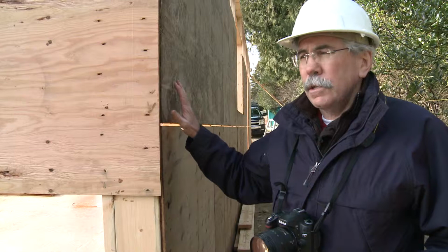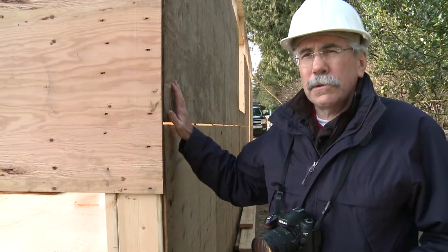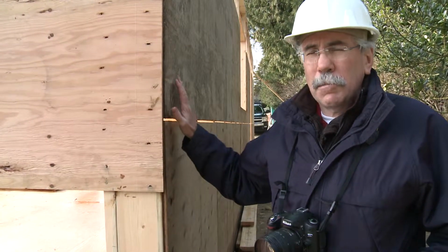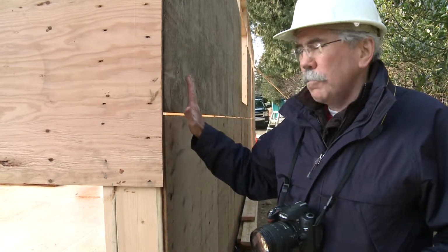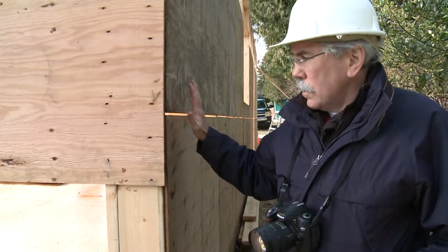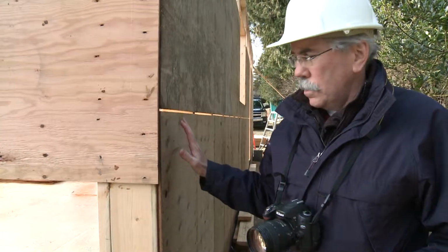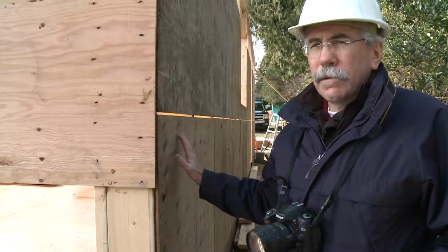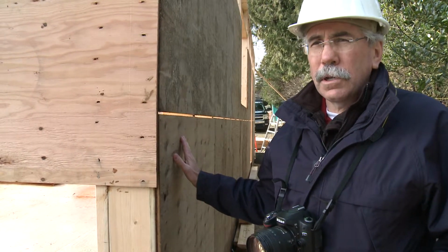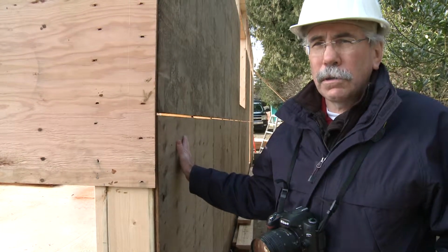And this is simply because the wall is so highly insulated and such little heat will pass through the wall that there will not be much of a drying benefit from heat loss through the wall. Also, being a north wall, it never sees any sunshine to help dry it out. So what the building envelope engineers have advised us to do is to use preservative-treated plywood on the north wall to prevent the possibility of that moisture causing any kind of mold growth or rot in the sheathing.